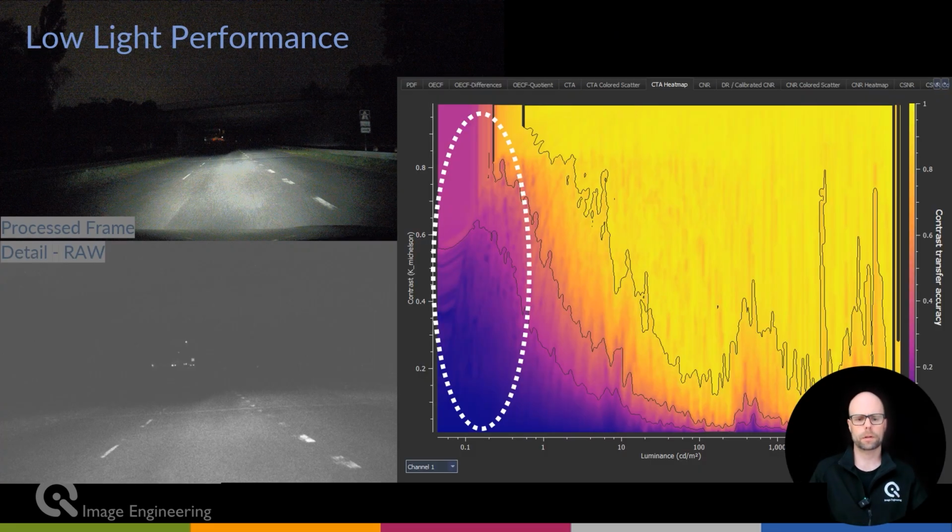So here's the example where we have a road. Only the headlamps are active, but because I'm driving relatively fast, my camera system should look beyond the headlamps. So that means what I need to see is really the low light performance of my camera. So for that, I have a look at the left region of my map. What you see here is more like bluish purple.